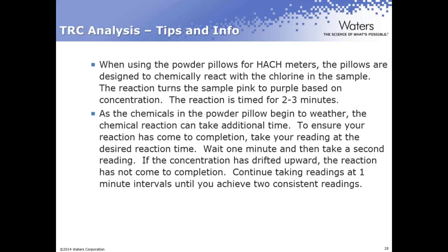I get so many phone calls where people say, I reported a low number, but I took a phone call or somebody asked me a question, I turned around and I looked at my meter and the value was higher. And the reason, again, is that the chemicals aren't completing the reaction as quick as they do when they're fresh. It doesn't mean that they're bad. It just means it takes a longer period of time.